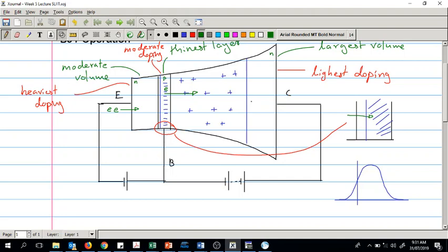The lighter the doping concentration, the more the volume that will be occupied by the depletion layer. So the acceleration process will take place throughout a larger distance in the collector, and you have only a smaller distance to be traveled. It is like you go at 100 kilometers per hour on the highway and put it in neutral by the exit way. You have enough energy to travel till the toll gate, whether it is a manual gear or auto gear, without throttling you can reach the toll gate without any problem.